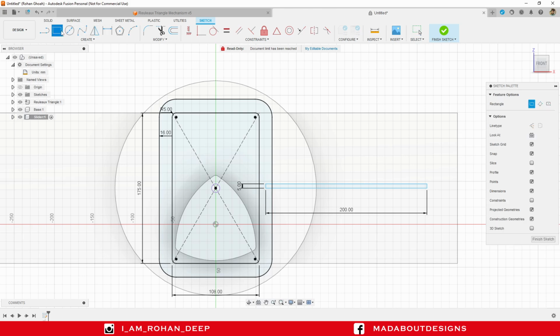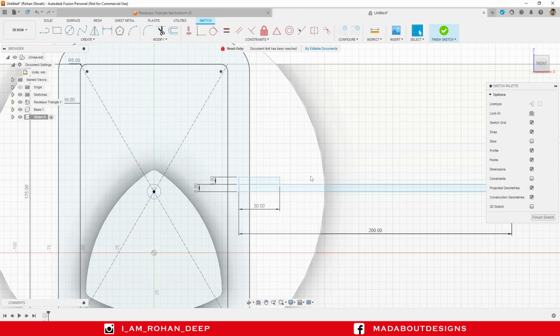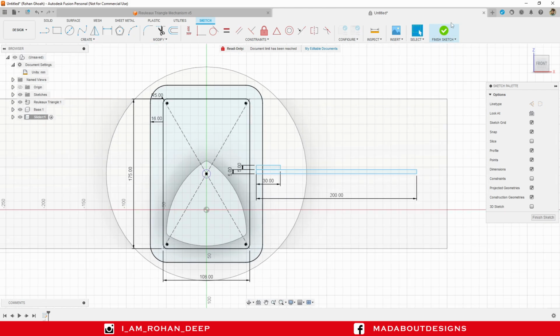Draw another 2-point rectangle. Select the first corner here and give it a dimension of 30 by 5 mm. Press enter. Now it looks good. Finish sketch.